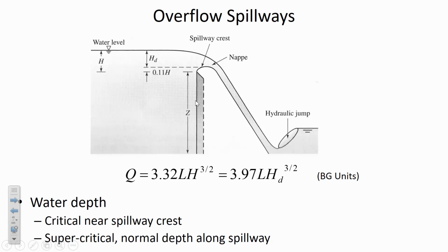So one of the calculations that's pretty important is trying to keep track of the elevation of the spillway, because there's a lot of things upstream that could be submerged if the spillway height is too high. Now remember that ordinarily the water isn't going over the spillway, so it could be years and years before the water levels get high enough that the people upstream are going to be affected by the spillway crest elevation.